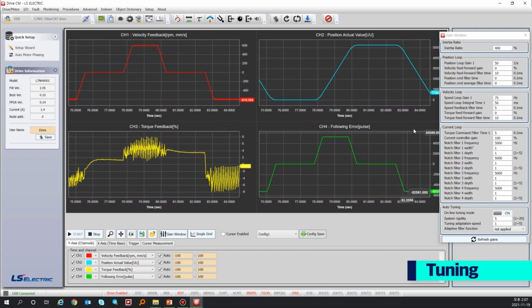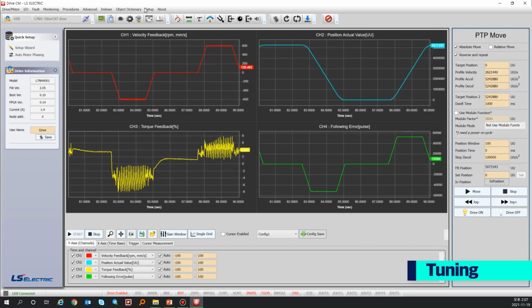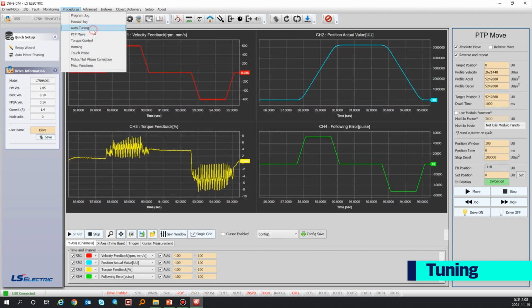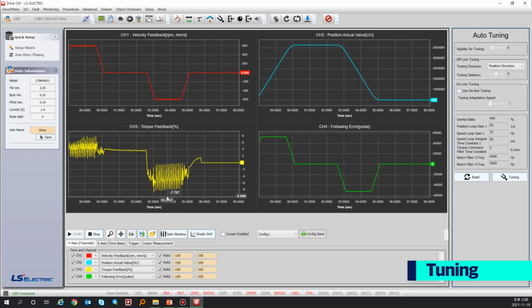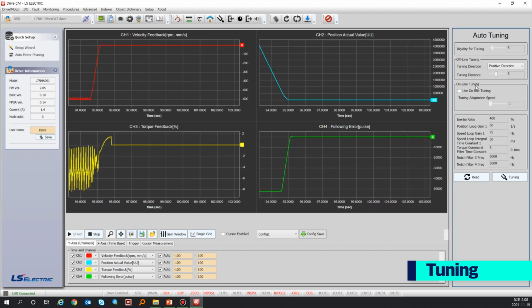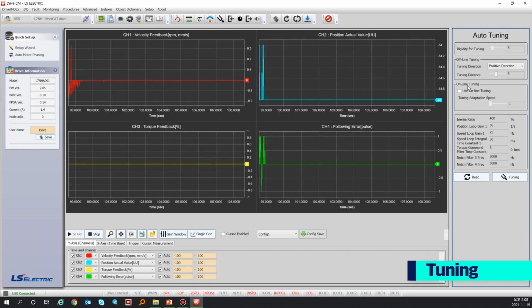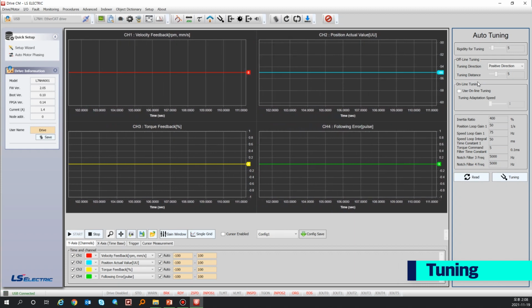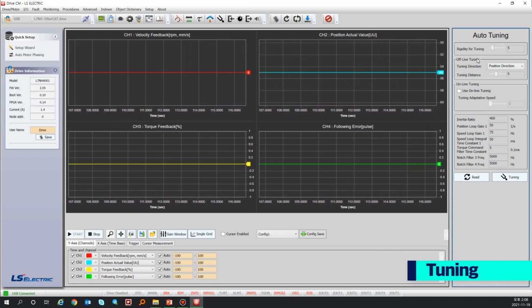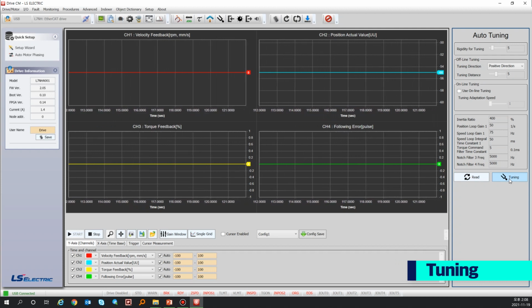Meanwhile, Drive CM offers auto-tuning. Click Auto-tuning in the procedure. You can see the auto-tuning window on the right. Auto-tuning provides two methods: offline tuning and online tuning. For offline tuning, set the rigidity for tuning, tuning direction, and tuning distance, and press the Tuning button to find the tuning value after 3 repetitions.